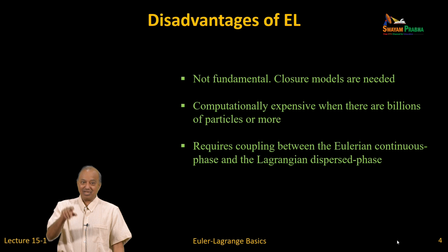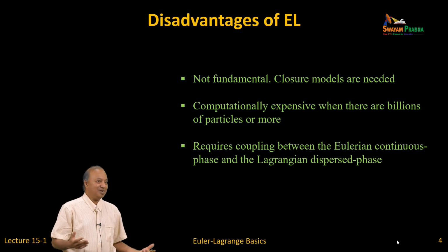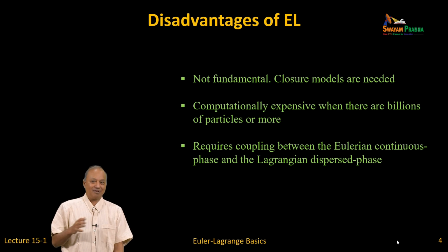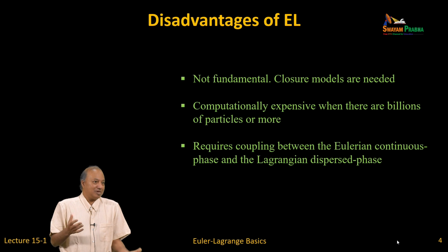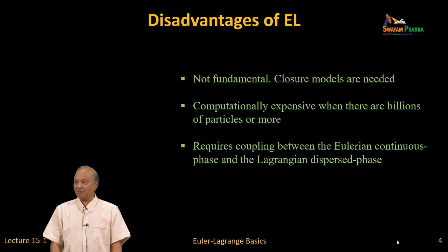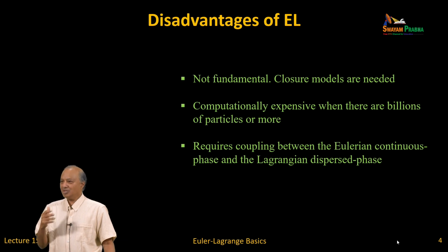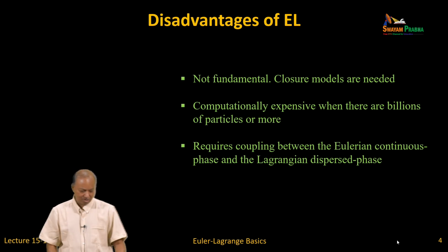And if you say one cell has a particle and puts a lot of force, and another cell no particle, you are going to have tremendous feedback force that you apply is highly noisy, it looks like garbage. Okay. And when you do the simulation and you plot your velocity, etc., it will look very noisy. Okay. Therefore, Euler-Lagrange simulations, you really want smaller particles, several of them per grid. Okay. Those are some general principles you want to follow in Euler-Lagrange scheme.